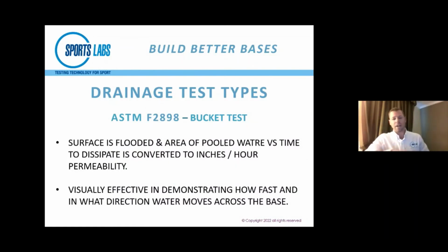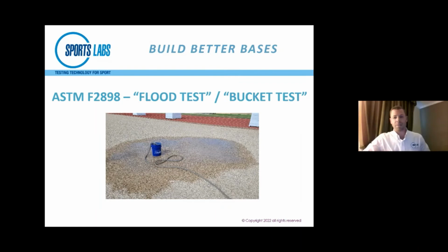In this photo here, you can see the area that it's moved out to. You can see standing water in certain areas. And then based on the area that it covers and how much water we've applied, we're able to calculate a rough inch per hour drainage capacity for the field or the surface.